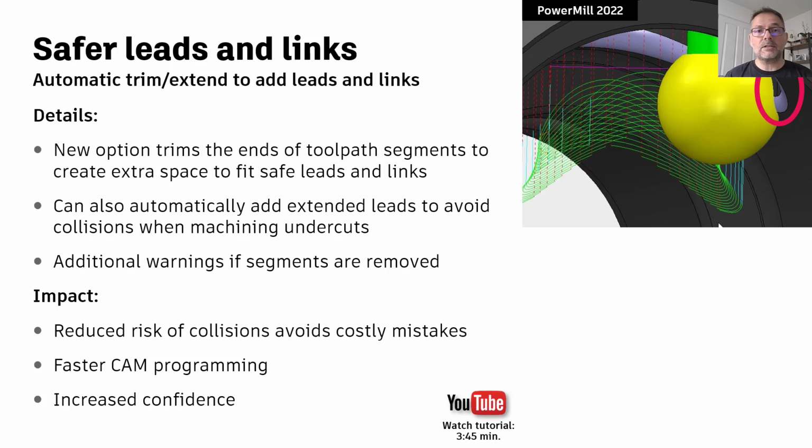Now, we have asked PowerMill to apply horizontal arc moves to this toolpath, but they haven't been applied, and as a result, PowerMill reverts to the default lead in, lead out move, which in this case is a vertical move. And you can see the consequences of that are that the tool collides with the workpiece during one of the approach or retract moves. This is clearly not acceptable.